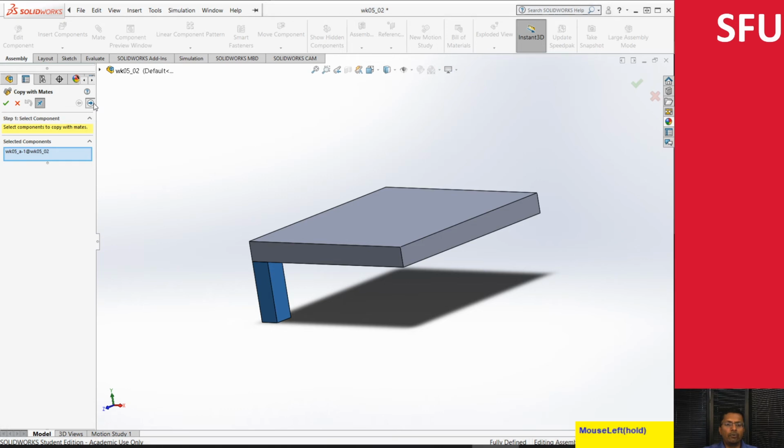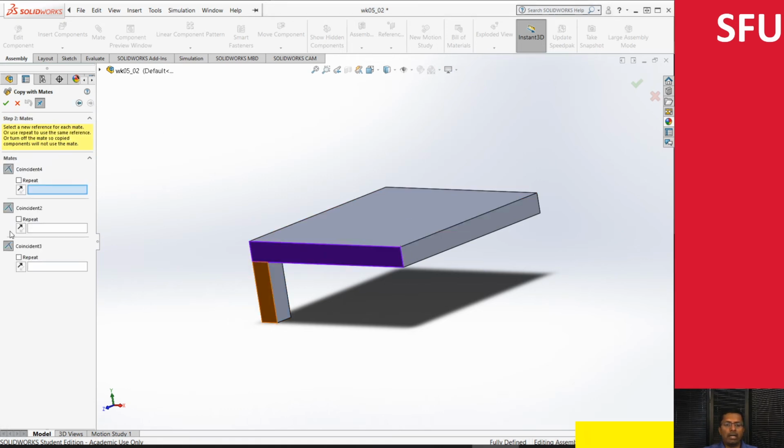So let's move forward. It's already copied with mates, and now it's looking to paste all of these objects, or basically paste this leg in multiple locations within my assembly. So I can go through this. I'm going to want to place one leg over here.